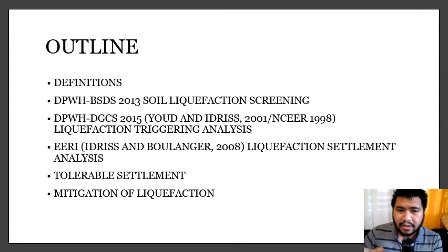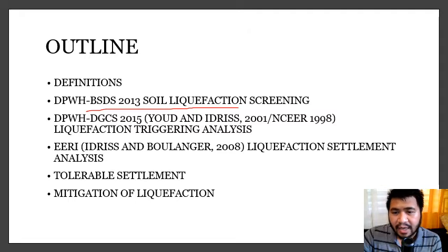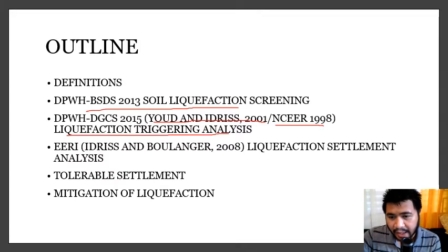And this is just the general outline of the lecture for today. We're going to be talking about the liquefaction screening process based on the DPWH Bridge Seismic Design Specifications 2013, as well as the triggering analysis, which is based on Youd and Idriss 2001, also known as the NCEER 1998.